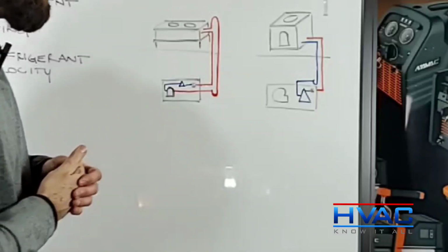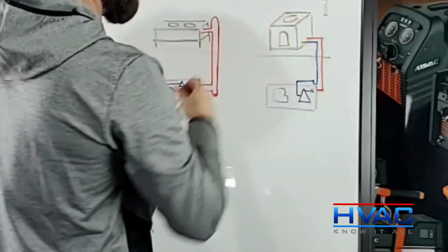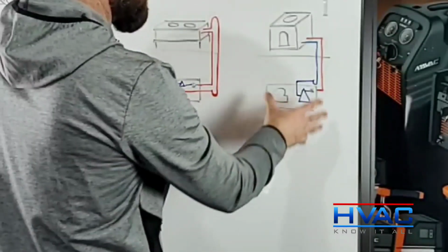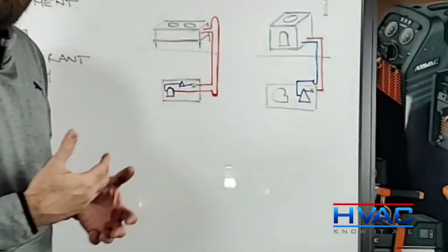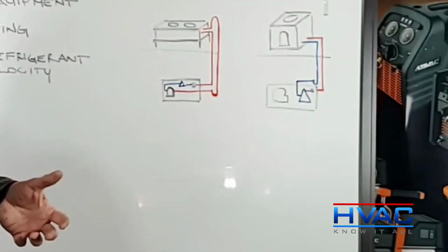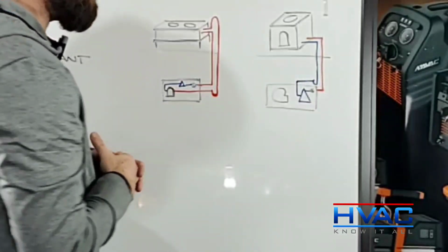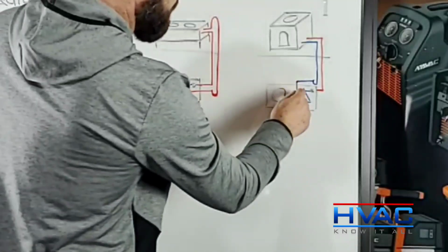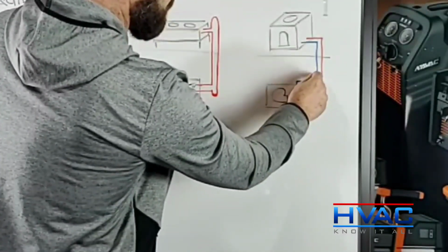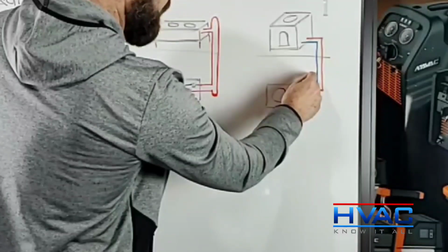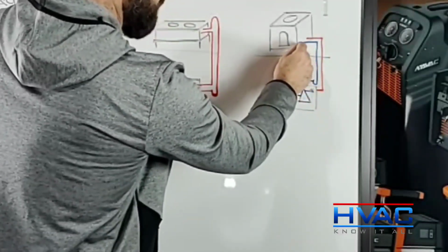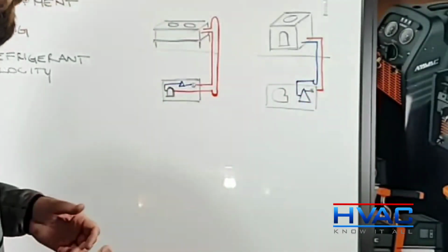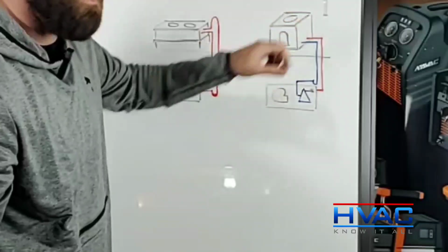And what a double riser is, if this compressor, let's say it could run at a variable speed or it can unload because the load is changing inside the room and the pressure is dropping lower than normal because of the variable load. If it doesn't have enough velocity to get up this pipe, what I've seen in the past is a double riser where another smaller suction line will come off of this. It will be trapped and move up to the condensing unit. Now that smaller line is going to have more velocity. That velocity is what's going to take the oil back to that condensing unit.